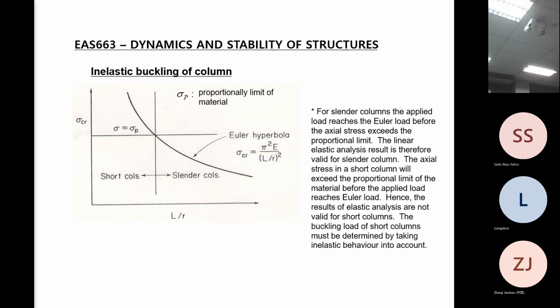Therefore, the results of elastic analysis, what we have done here, considering elastic behavior, are not valid for short columns. The buckling load of short columns must be determined by taking inelastic behavior into account.